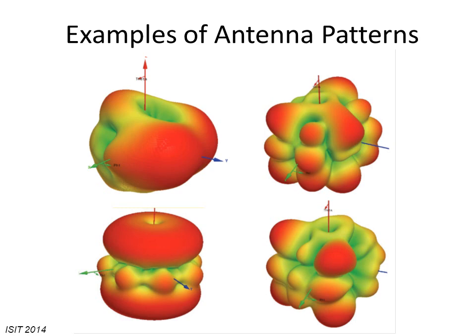So here I have an example of the antenna patterns corresponding to some of the switching patterns. As you see, the antenna patterns have some weird shapes, but each of them, because the signal gets propagated through a rich scattering environment, will correspond to a constellation point at the receiver with the components I and Q independent of each other.